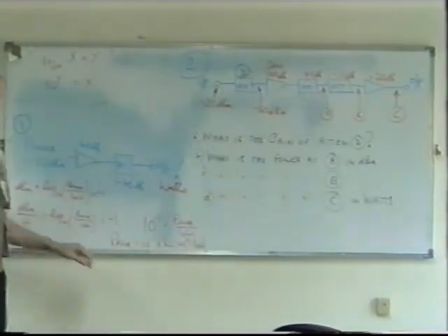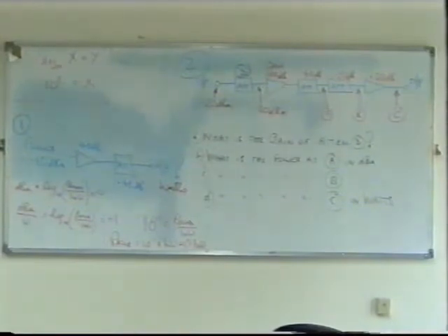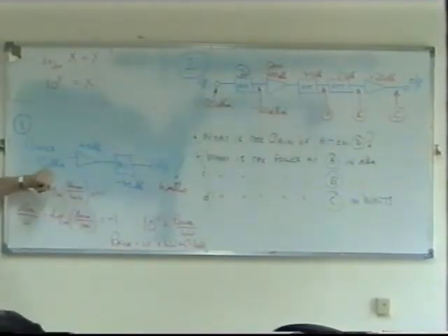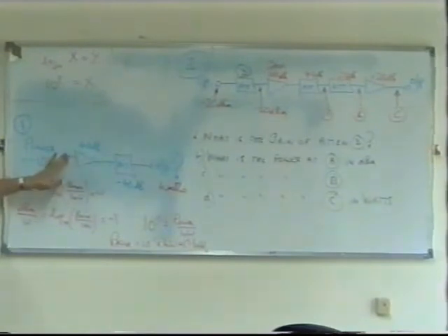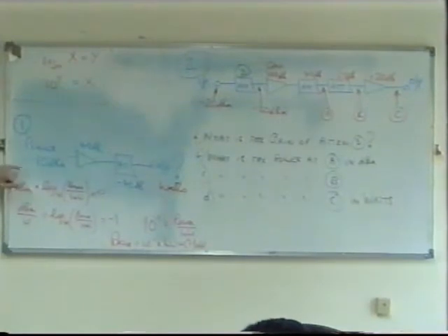First of all, if we have a look at question number 1 that I completed on Wednesday, we'll see the advantages of using dBs and dBm. Here I have an input power. Now when you see dBm with the small m, that means it's a power measurement. If it was just dB, it's a power ratio. So dBs itself doesn't tell you what power it is, dBm tells you the power. Now we have an input power here of minus 10 dBm. Okay. When you see the minus sign, what does that tell you?